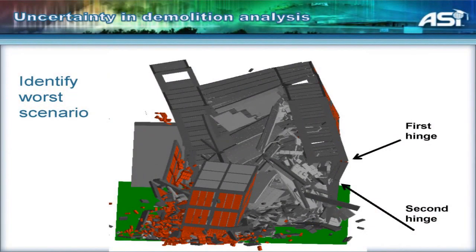So you would have a very good hinge down here, which is where you want the structure to fail so that it hinges and falls that way. But depending on how this reinforcement is, you can have a second hinge here, and then you have a part that would fall in the wrong direction. You have 2 hinges along the same column, and part of it is going to fall the wrong way.